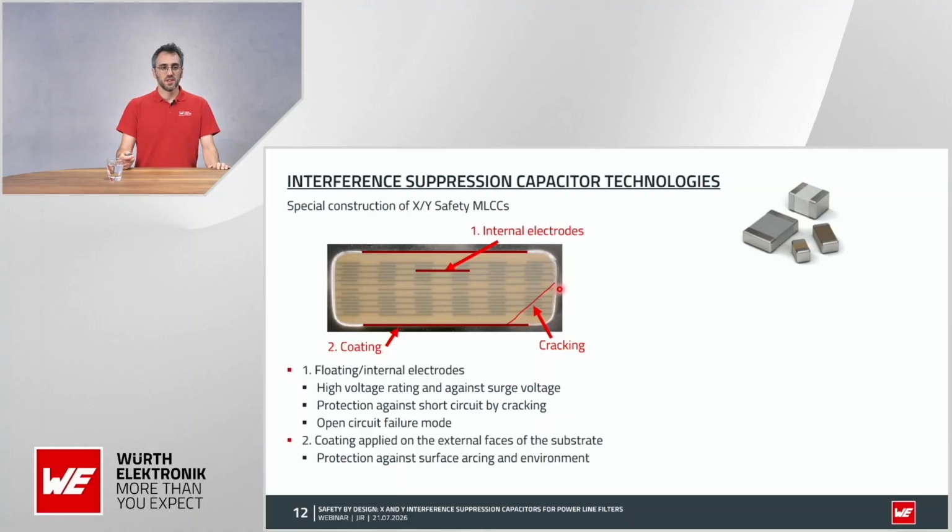Now, another property is the coating on the external faces. This is normally applied to improve high voltage performance, avoid arcing, especially when there is some dirt or some environmental effects on the surface.